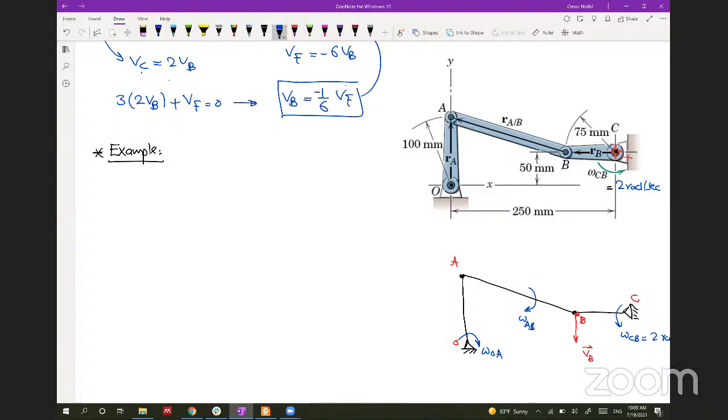Let's get the velocity at B. You have 2 ways to solve this problem. Either you are familiar with the directions of the velocities and the omegas from the body geometry, and it's very easy to do it in terms of velocity and omegas, but it will be more complicated if you have acceleration, alpha and a. So I would recommend going the other way, which is to solve it with vectors. Let's do both: with vectors, and in the scalar form.